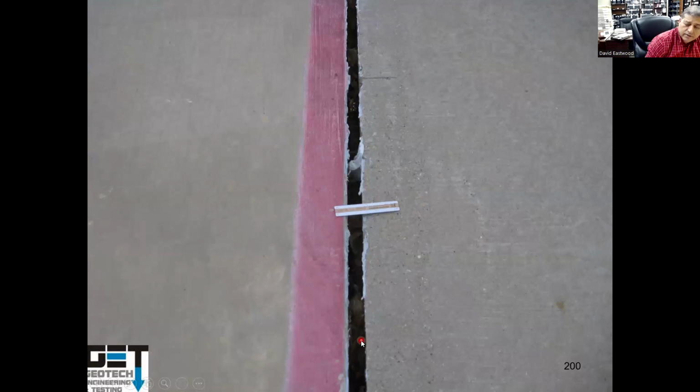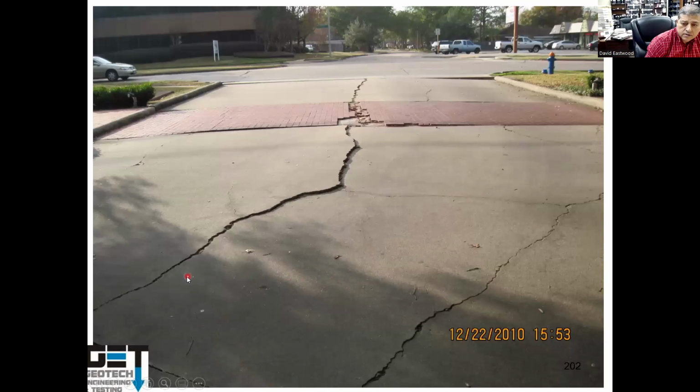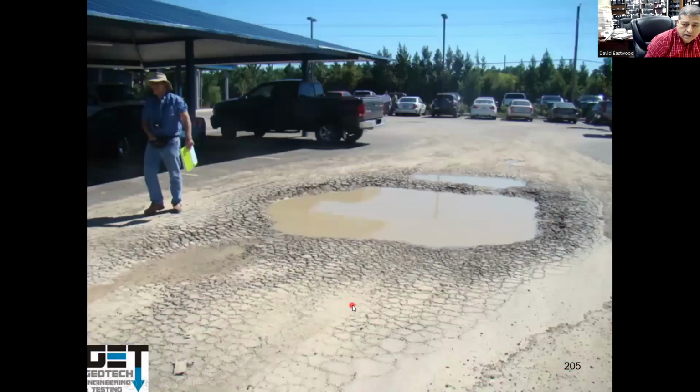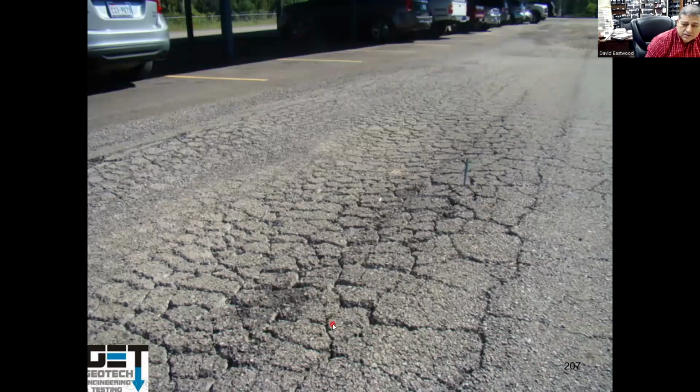Expansion joints whitening. This is Flower Mound near Dallas. Again, more pavement cracks out there. This is a Wilcrest. The Montessori School. Cracks in the pavements. Not that many control joints. Asphalt pavements. This is near the Bush Airport. They put asphalt here with not much of a base and the subgrade stabilization. So this is a parking facility. Developed many cracks and distress.